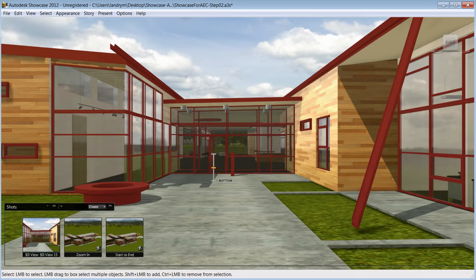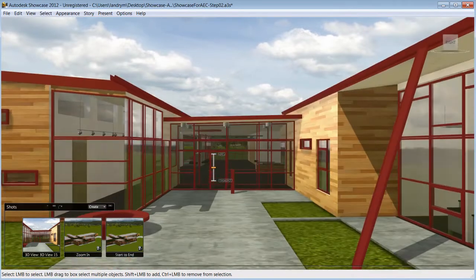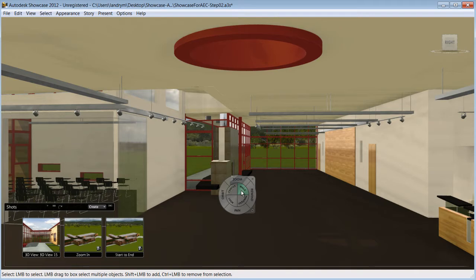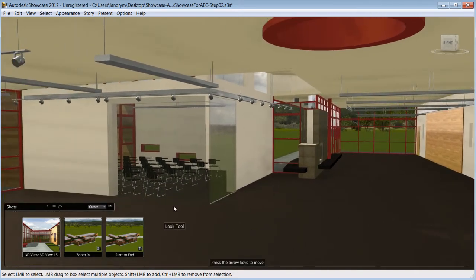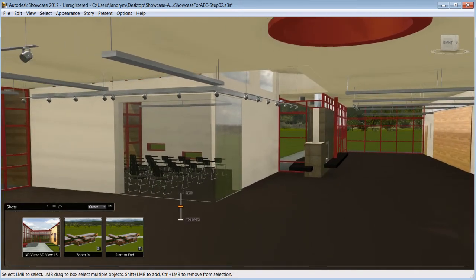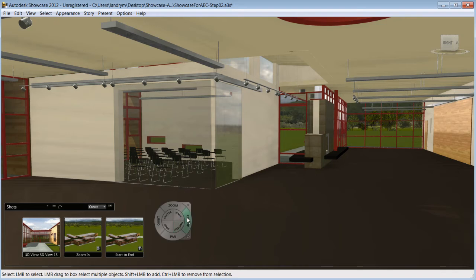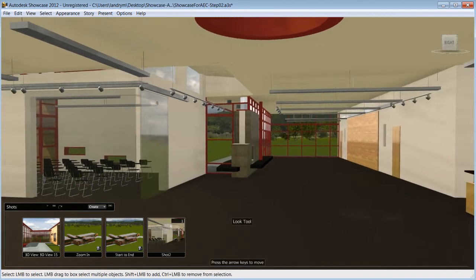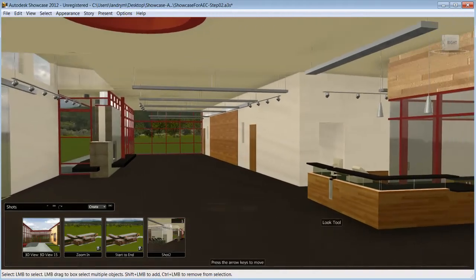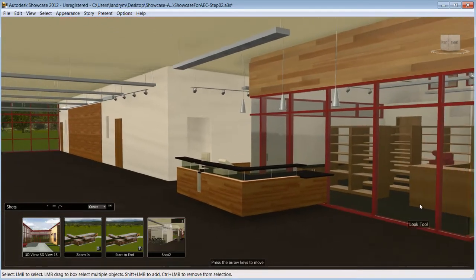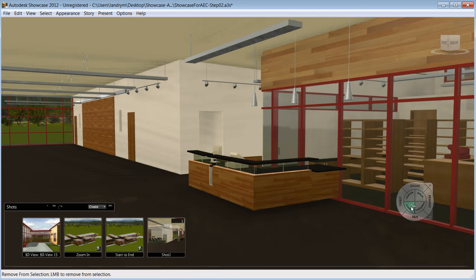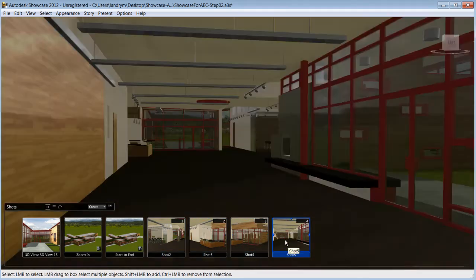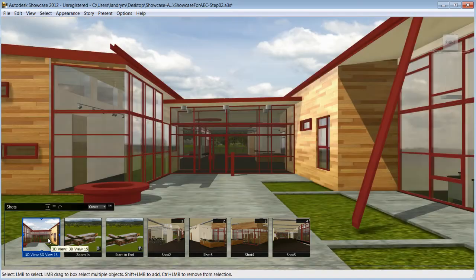You will be able to explore and experience your design in real time with Steering Wheel, the navigation tool. The exploration of your model is made easy with the definition of Walk Zone, a one-click process that will constrain your movement to walkable surface and generate a walk zone. As you're walking around your space, you can easily press the Ctrl key and a number from 1 to 10 to save additional still shots that you can retrieve easily by pressing the shortcut number you have assigned to each shot.